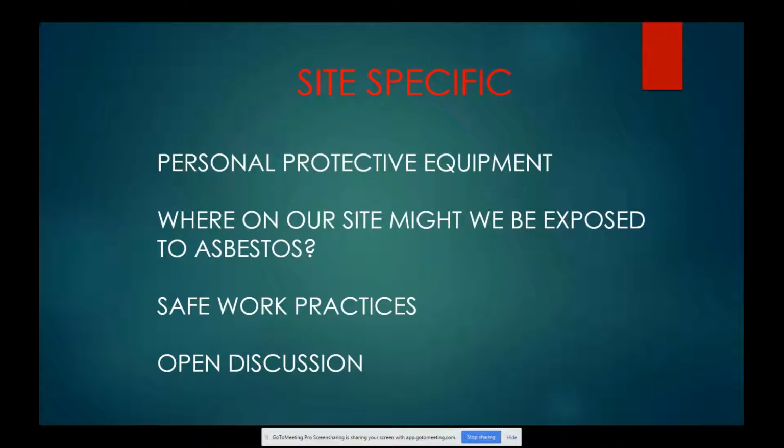Personal protective equipment. Us on the working face, we typically are in equipment, but if we have to deal with asbestos, disposable overalls are highly recommended. It makes decontamination easier, and what we use is a full body Tyvek if we have to physically work with asbestos. Of course, you need your high efficiency particulate air filters that have been fit tested, your gloves,